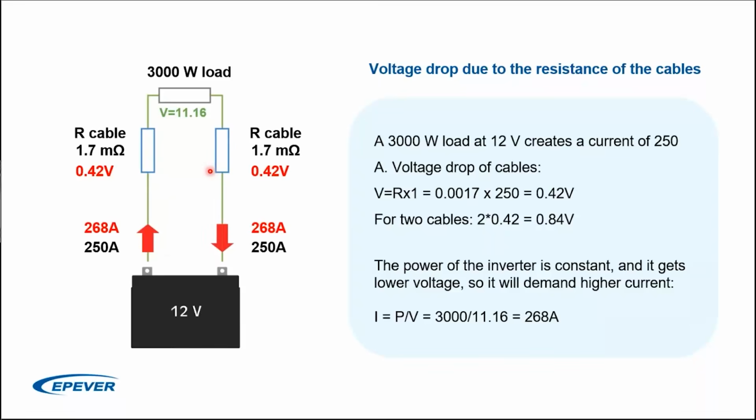One of them could be the voltage ripples, the DC ripples in your system, because this will happen frequently, and the battery will try to compensate for the amount of current that is needed. Then you will have a ripple, and this ripple will shorten the lifespan of all the components in your off-grid system. So with this example, we tried to demonstrate that if you have even a very low and negligible resistance in some place in your off-grid system, then you are going to have some troubles.